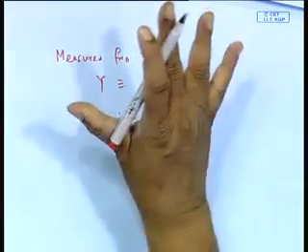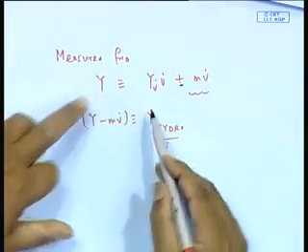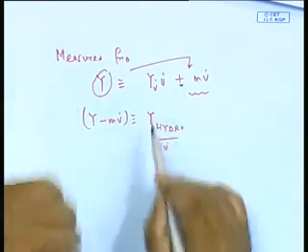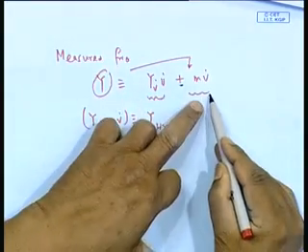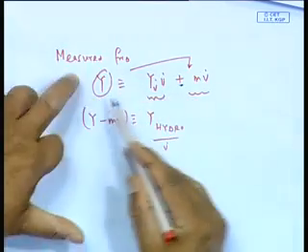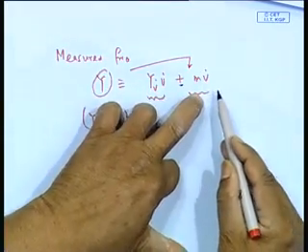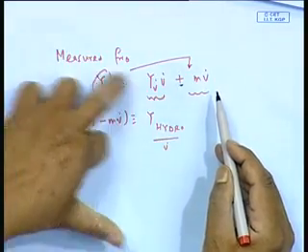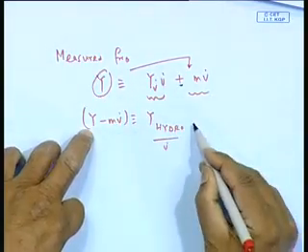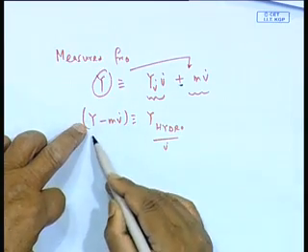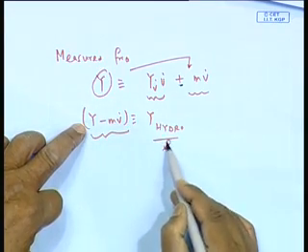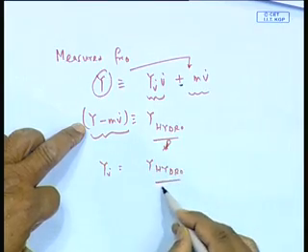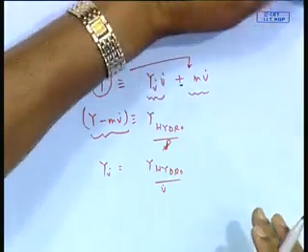Okay. Same thing. I am just trying to explain that the measured forces will always include this. As a result, if I want to find out the hydrodynamic force, measured forces always include body inertia forces. So, if I want to determine hydrodynamic forces, first of all I should take this off from here and then divide by v dot to find out the derivative. That means this would be my hydrodynamic force, and therefore Y_v dot is Y hydro by v dot. Okay. That is what we have done.